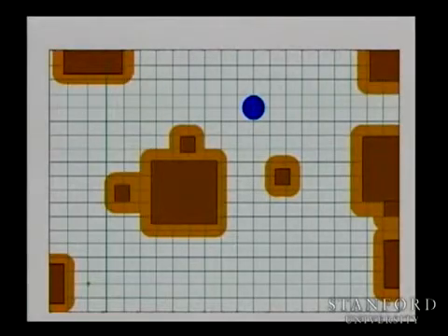And what we can do is put a grid around it and then plan the path of the point around this grid so that it doesn't collide with the grown obstacles. Then when we get back to the circular robot, it's not going to collide with the obstacles itself.